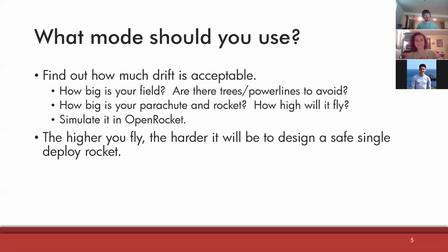My personal recommendation: when you're doing an L2, it is a great opportunity to learn dual deploy. So I think it's probably a good idea, although you don't have to. Generally, it definitely is an unreasonable option to do single deploy if you're flying on a smaller L2 motor.